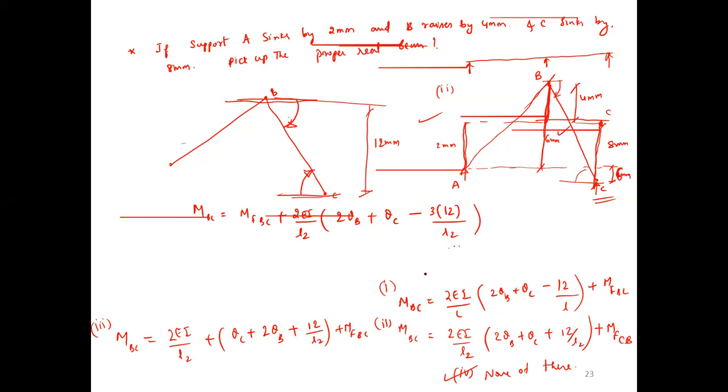And also one more thing. Here I have not mentioned L in mm, so L is in meters. In some problems, they will mention L in meters and deflection in mm. On that condition, you have to divide that mm by 1000. You have to convert the given deflection into meters. Generally, it's a 20 marks question, so that kind of related question will not appear in MCQ.